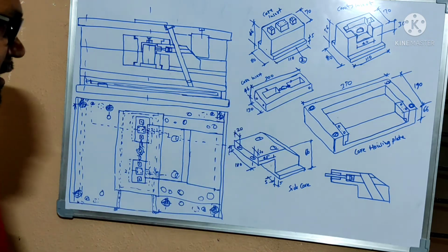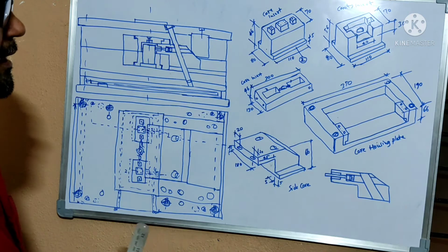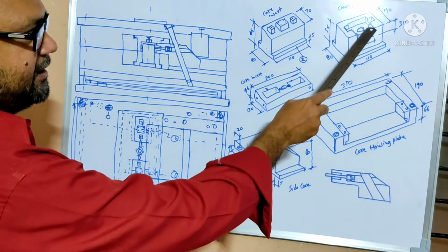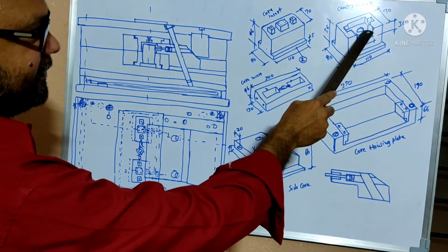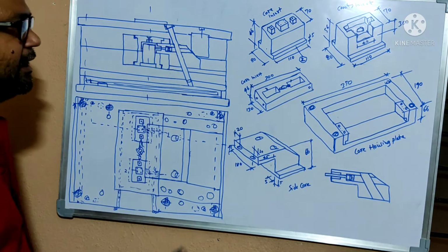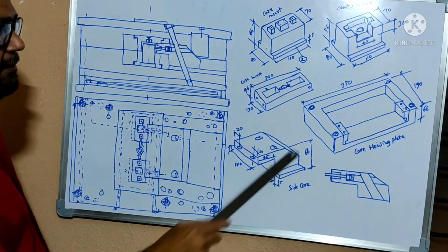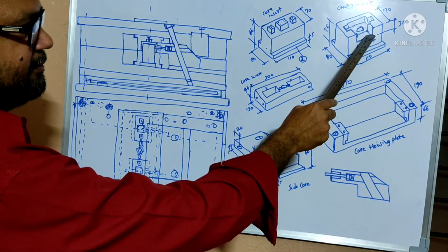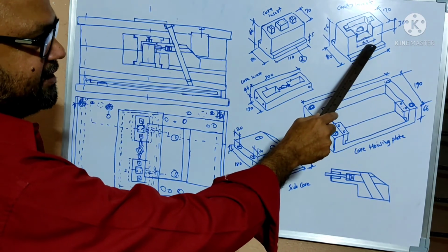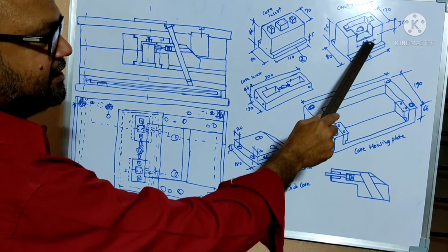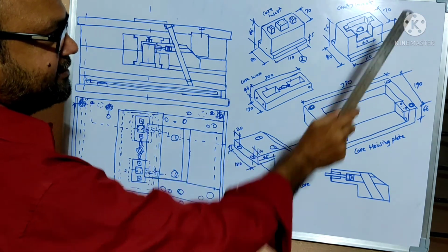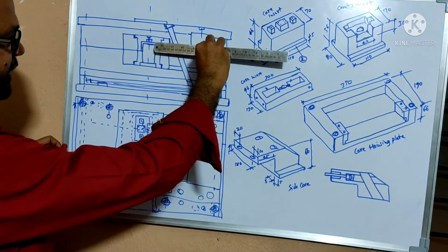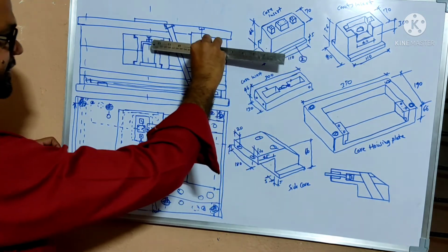The component has depressions inside, and here you are observing the depressions in the cavity insert, to get the component. At the same time, the recess or sectioning is done to some of the material. The dimension I have given for this section is 40, and the length of this one is 30, so that the side core can move in and outside.